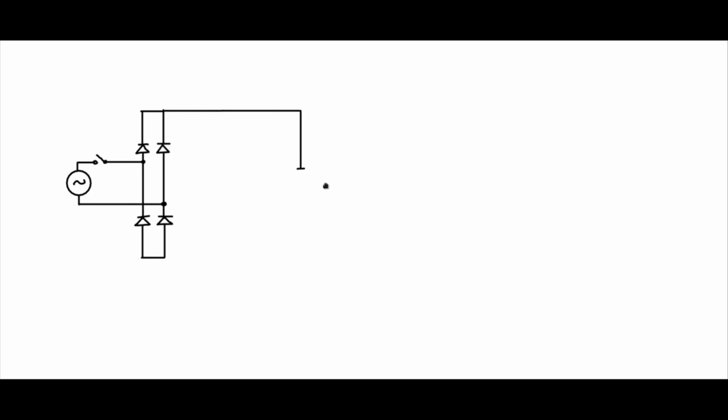Now this portion we know, this is the sine wave source followed by a rectifier. And let me draw the load R0 first. So this is the R0 that we connect across the rectifier. Normally we would have connected a capacitor like this. However, we want to modify this into a power factor improvement configuration.